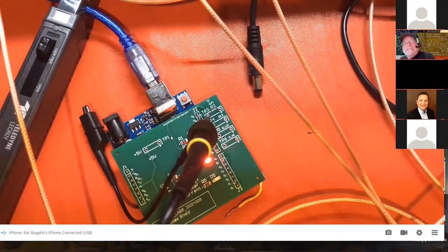Okay, good, thank you. And the last question is, what are the advantages of using a high resolution scope in terms of measuring emissions? Well, in this example that we looked at, we're looking at near field. Again, it's the difference between near field and far field. For the smaller signal levels that we're looking for, we want to first have low noise in the amplifier, and generally the higher bit resolution scopes, our scopes, have lower noise figures than 8-bit scopes, for example.